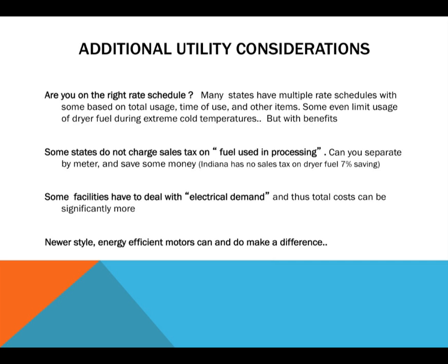Some facilities have to deal with electrical demand. Anybody in here have a demand factor that they have to deal with at your facility? Yeah. Wow, that can add up. A number of years ago, one of the facilities that I managed, our actual kilowatt per hour charge in the rate schedule was 5.5 cents. But once they added the demand portion, and we had a lot of horsepower, and you're bringing in a lot of horsepower at one time and all that kind of stuff, our average cost per kilowatt hour was 12 cents. Better than double the actual cost.